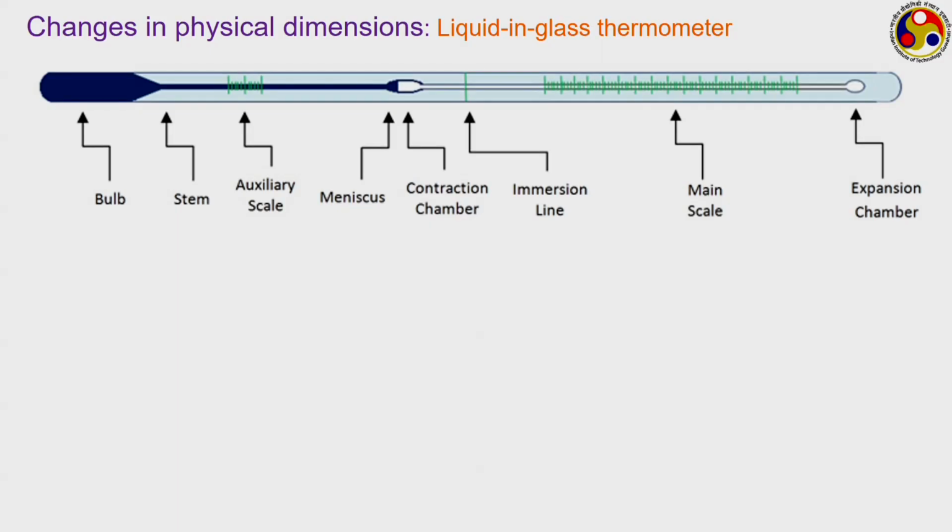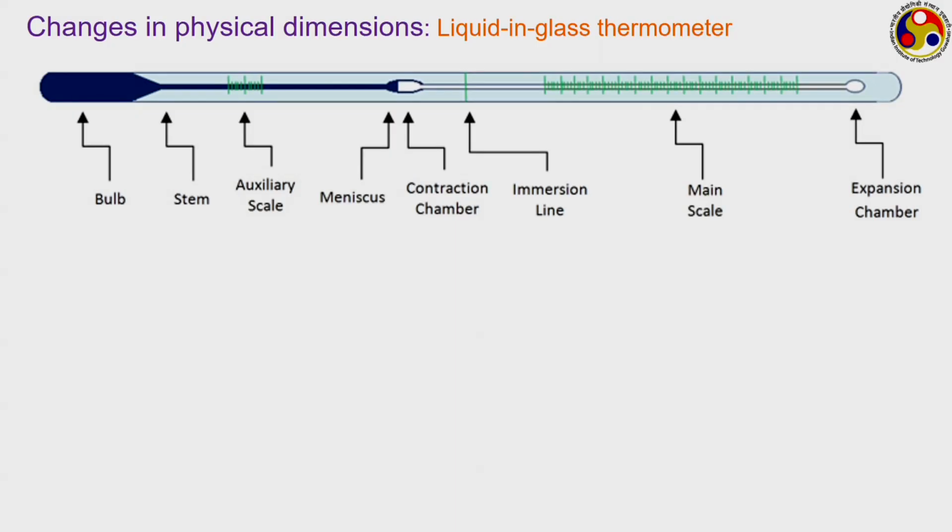The other option, the very popular one, or the most popular one that you know, is the conventional thermometer. Something you probably knew by the term thermometer before this lecture, but the more specific name of this one is a liquid in glass thermometer, where we have a capillary tube through which some kind of temperature sensing liquid can move up and down.